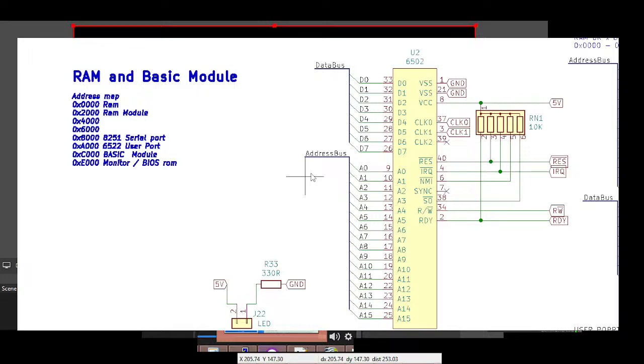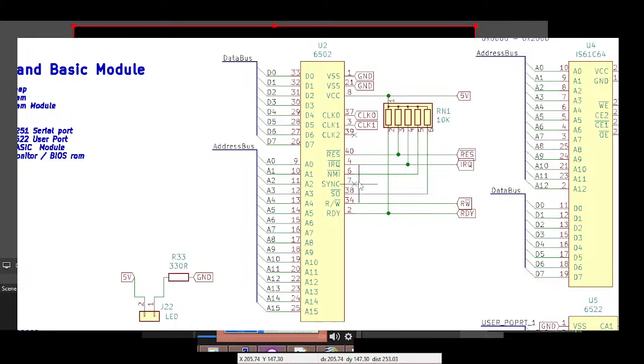Okay, so let's just do a quick tour of the 6502 that I have. This is the working one. So your processor, we have, of course, the address and data bus. We do have the read-write signal across. You can use the IRQ and the ready one. I'm not using the non-maskable interrupt. We could use that on a different board. Sync's not connected. Okay, this isn't the right one. Yes, it is the right one. Sync's not being used, and I can't remember what that one is. I think it shows where the processor is in